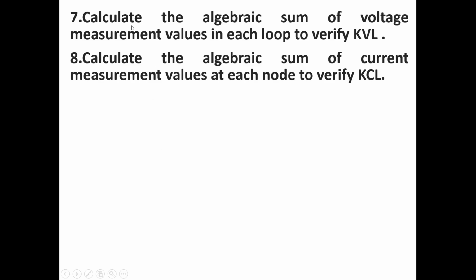Next, calculate the algebraic sum of voltage measurement values in each loop to verify KVL, and calculate the algebraic sum of current measurement values at each node to verify Kirchhoff's current law.